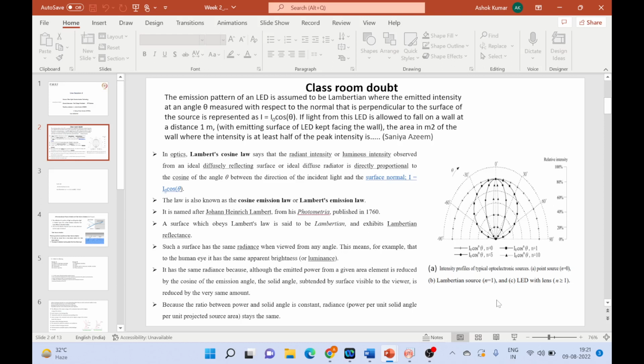We like the emission spectrum of the light source itself to be very sharp at one frequency. For example, we use lasers at 1550 nanometers these days, and we want this to be very narrow. When we modulate some signal on top of it, it will occupy some more bandwidth.